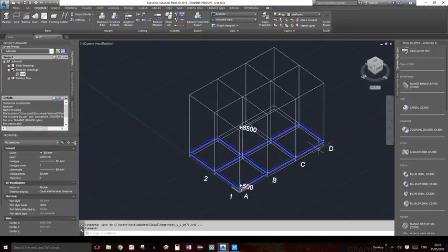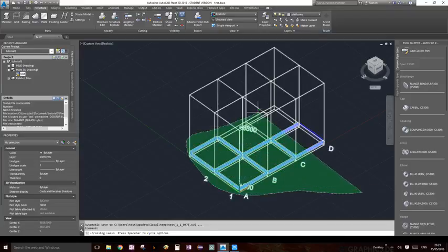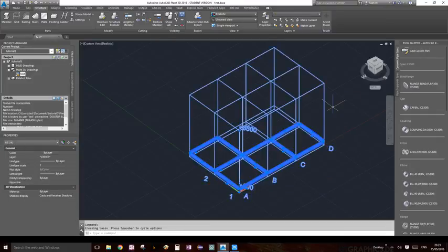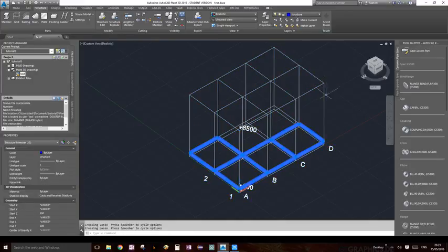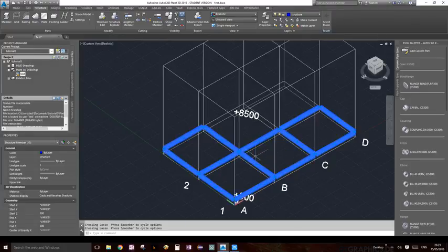Okay, so let's go ahead, and I'm going to use my green window. So I'm gonna click my left mouse button and just create the window, going from right to left. It's gonna select everything, but it also selects the grid. So every time you select something and you want to unselect it, you can still do the green or the blue window, but just hold down shift and then select, and everything but the ones that you selected is going to be deselected, which is kind of awesome.